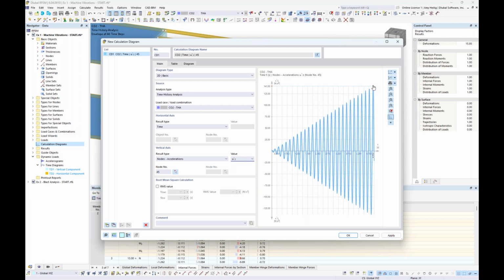But somewhere at the low end, it should be around 0.5% g, and somewhere at the higher end of acceptable tolerance values here is 5% to 10% g. But in any case, we are far over that with this particular structure. So we need to make some modifications.